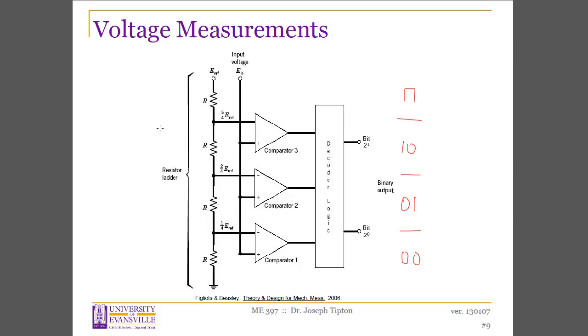On the analog side, then we have some sort of voltage range over which we are measuring an unknown voltage. Well, let's say in this example our voltage FSR is the terminology we're using. FSR is equal to 4 volts. That's our full-scale range over which we're expecting to measure some unknown voltage. It's got to fall in between that.